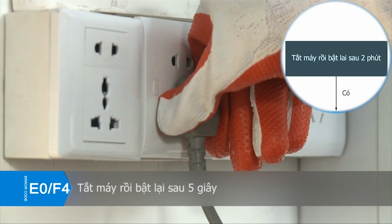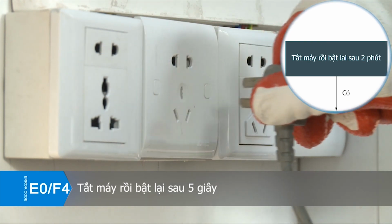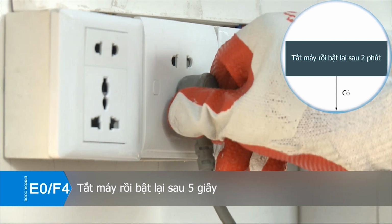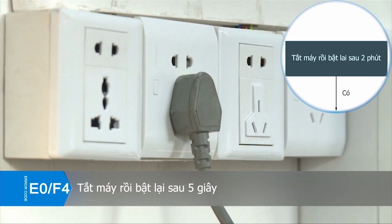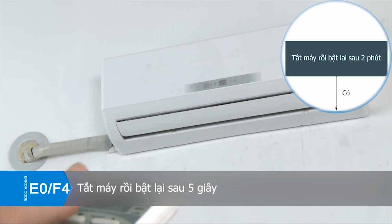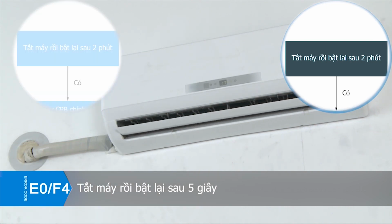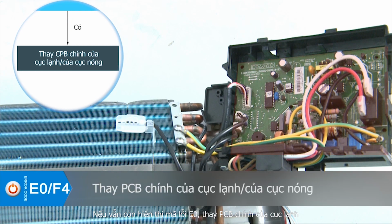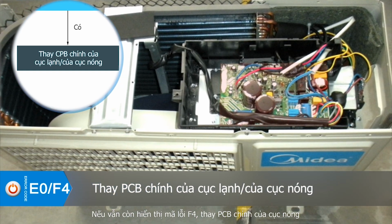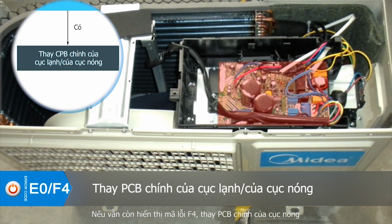Shut the power off, then turn it on 2 minutes later. If it is still displaying E0 error code, then replace the indoor main PCB. If it is still displaying F4 error code, replace the outdoor main PCB.